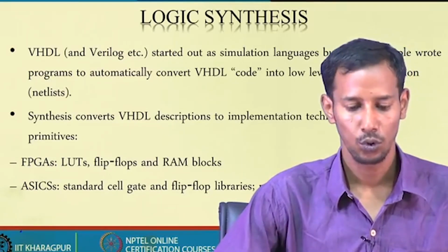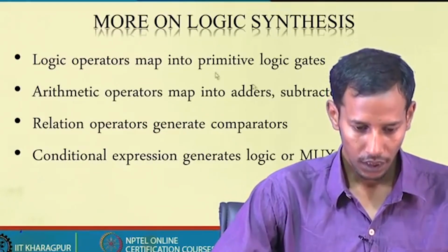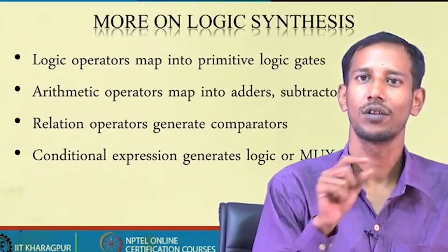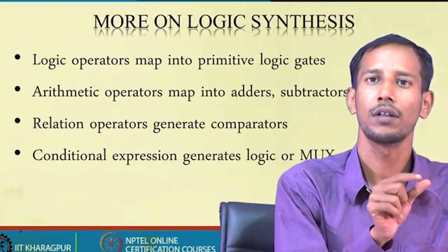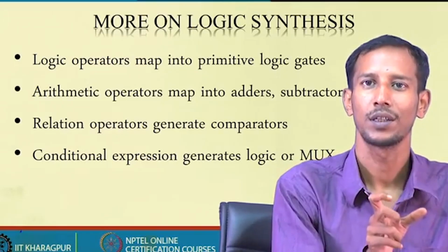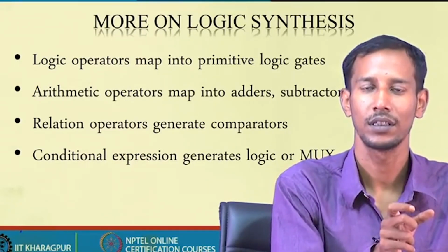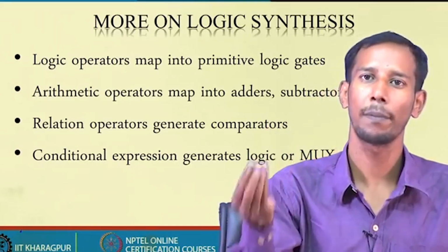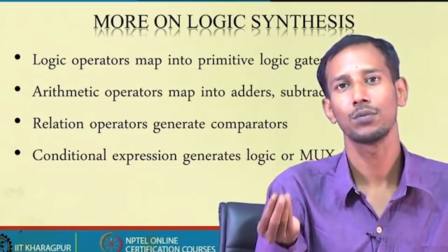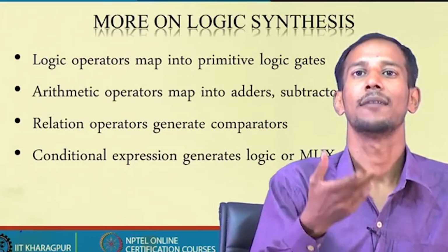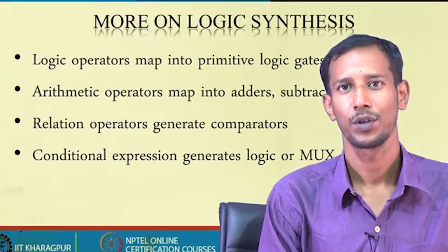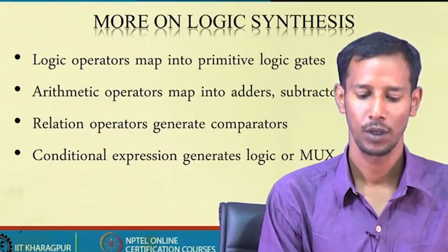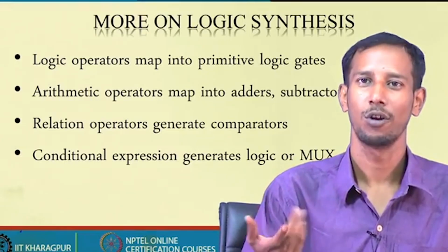So you have this particular information in your library. Whatever logical expression you are describing using the HDL language, during the synthesis those gates or those operators or those memories will be called to implement your particular system or the expression which you have mentioned in the EDA tool. That is the process of logic synthesis.